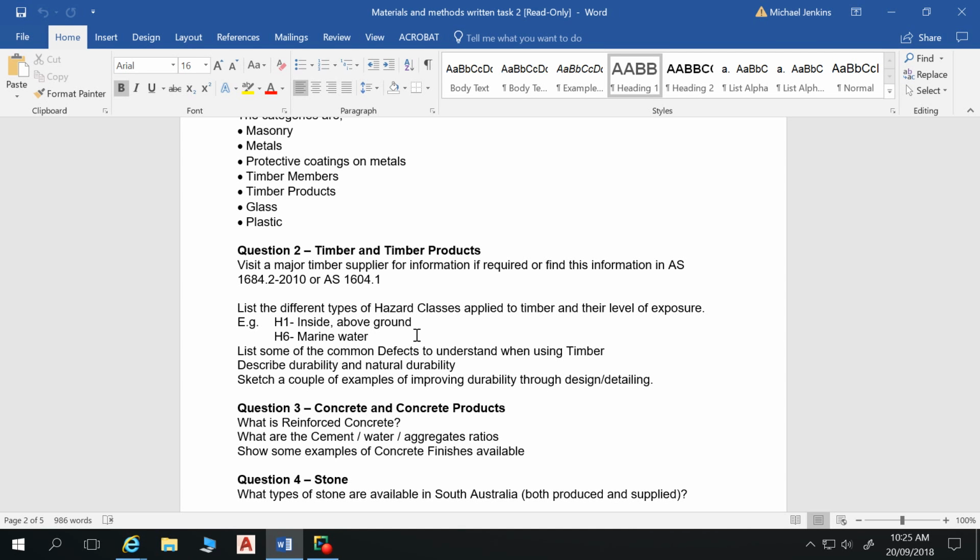Some other design details, like things that get rid of water. If I use a piece of timber on the top of a railing like this, so this is our railing, top of the balustrade, a really good idea is to do a slight sloping cut. Well, that's an exaggerated sloping cut, but a slight sloping cut, so that the water drains away from that piece of timber.